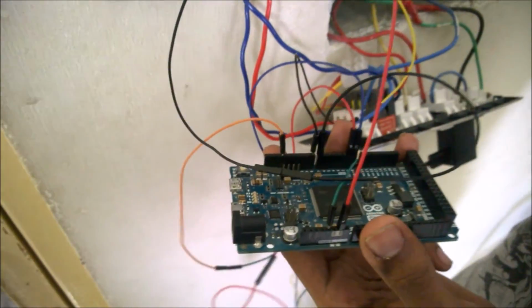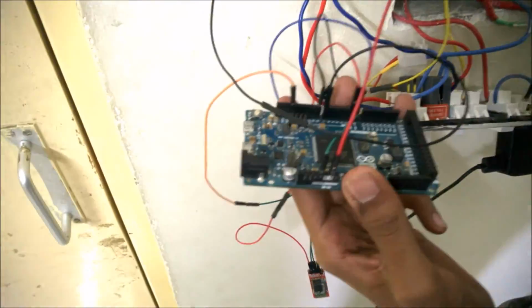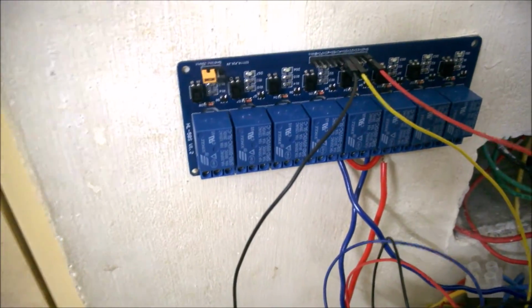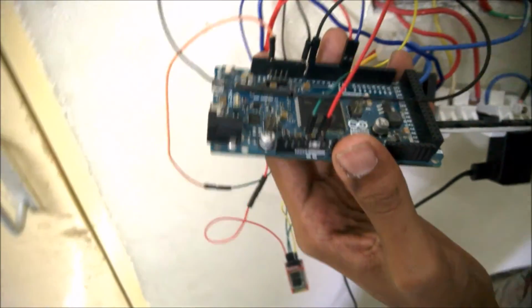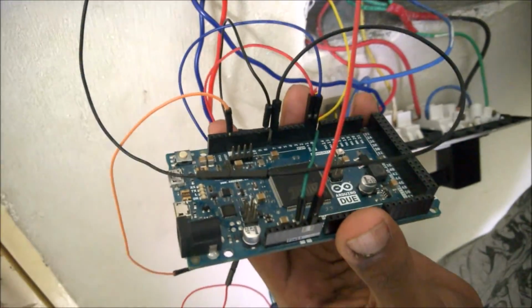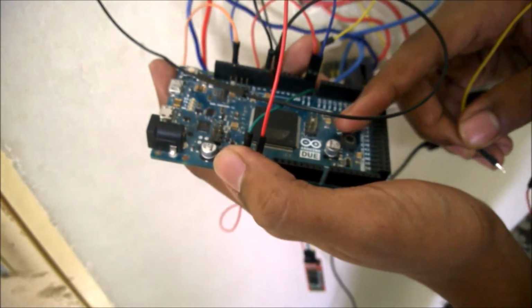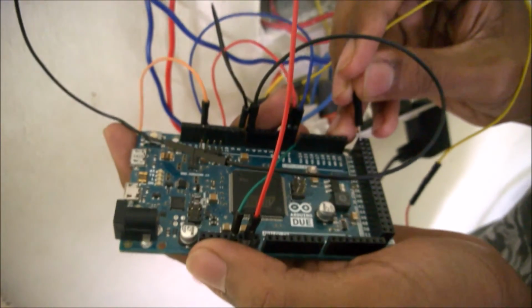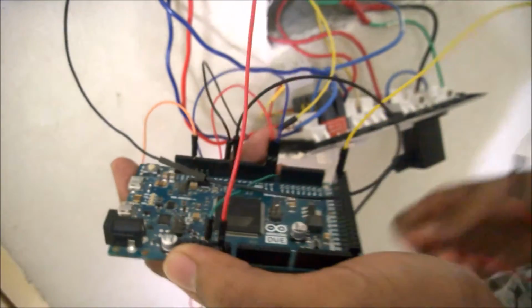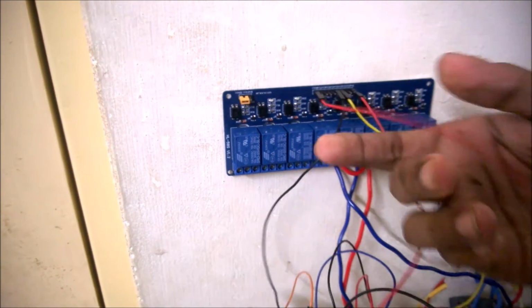Now here's the thing. If you see, we are running out of 5-volt pins. If you are working on an Arduino Uno, you will find that you don't have an empty 5-volt pin in order to power up the relay board. You have got only one 5-volt pin and you have used it to power up your Bluetooth module. So what could you do? One thing, you could use a breadboard. But we are not facing the problem because we are using Arduino Due, which contains multiple 5-volt lines. We'll be taking one of the 5-volt lines and connecting it to the VCC of the relay module. Now the connections are done.